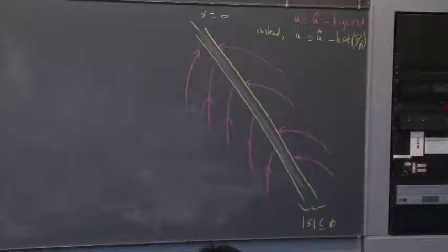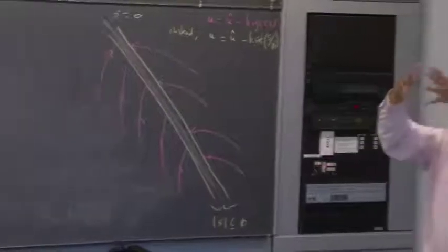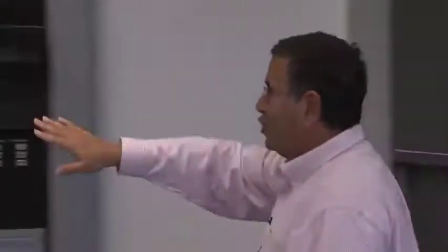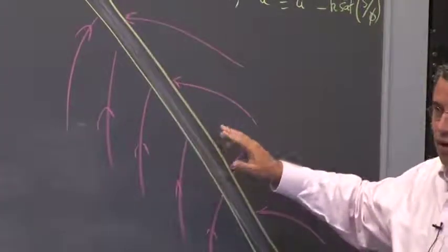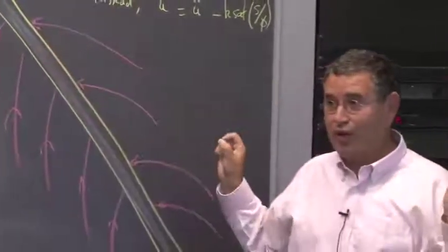So before, we said, starting anywhere, we reach s equals 0 in finite time, after which we stay on s equals 0 and we slide along the surface. What's the narrative now? Well, we were supposed to reach s equals 0 in finite time, but actually the control is not the same in this region. So we reach this region in finite time.